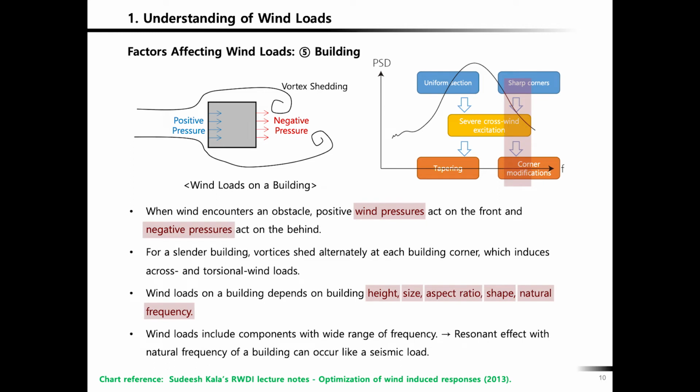If your building is located right there, maybe you have zero contents from that wind, then you have no dynamic effect. But for a tall building, anyway, you have certain frequency contents in that wind, so that it creates some kind of resonant effect. Of course, if you have no damping, it's going to be infinite, but you have damping, so there's a certain amplification. That's the same as a seismic load.